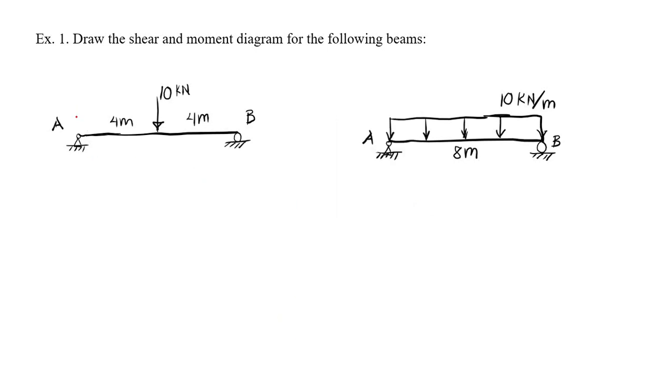Okay, we will project the sections of our beam. So when we draw our shear and moment diagram, our first step would be to solve for reactions.